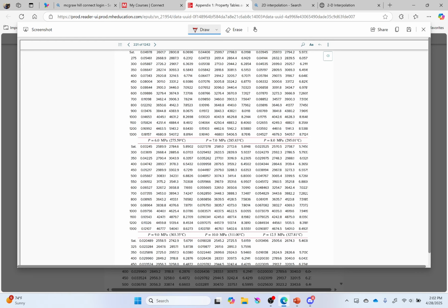That's way outside of what you can do by hand easily. And so I would strongly suggest you use like Excel. Excel has a 2D interpolation function. Python does. There's various little calculators online. And it'll take a little while because you're going to have to type in your values for each of these guys. And once you've done that, it will interpolate for you and tell you what your pressure and temperature is. You'll only need to know your enthalpies and your pressures and your temperatures. These would be like your x values, these will be your y values, and this is your z values when you're playing those functions.